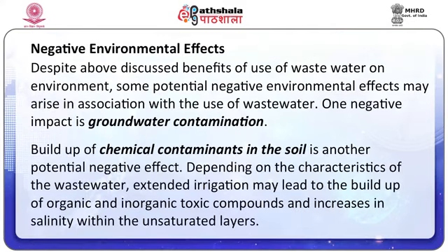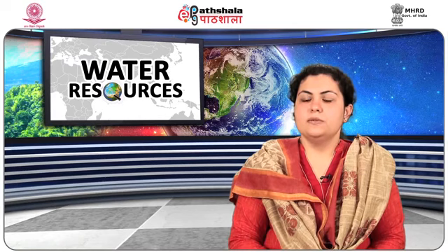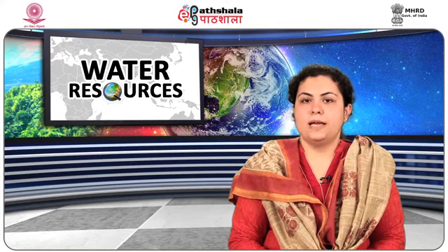Negative environmental effects. Despite the above-discussed benefits of the use of wastewater on the environment, some potential negative environmental effects may arise in association with the use of wastewater. One negative impact is groundwater contamination. The main problem is associated with nitrate contamination of groundwaters that are used as a source of water supply.